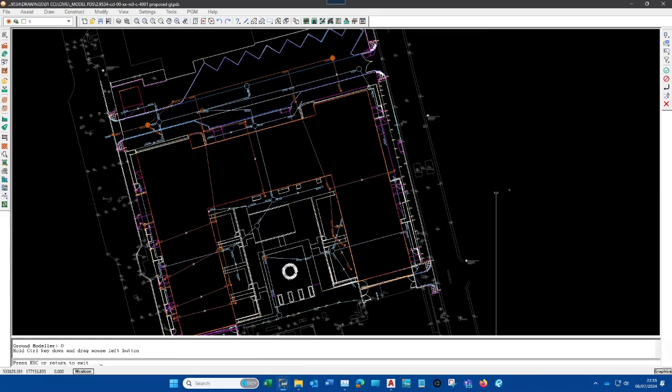You can hit the red circle and go no, because with PDS, you can't type no. Everything's done by hitting the buttons or using the pop-up windows. So that's what that's useful for. You're saying yes, do something, or no, don't do it, when the command line is asking you whether or not you want to do something.